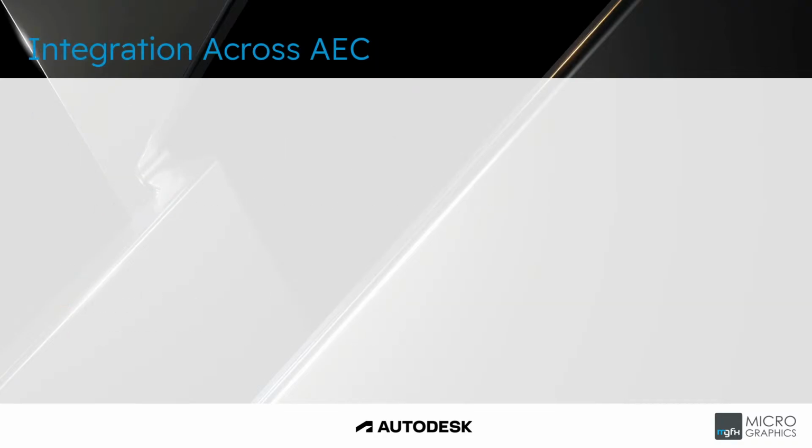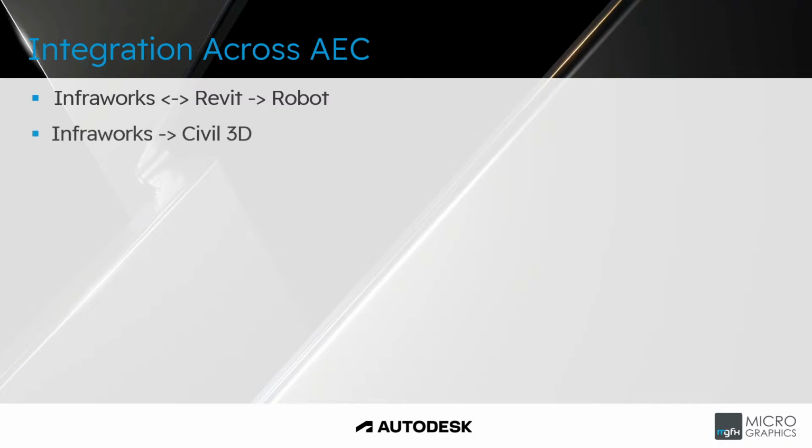Okay, and with our last section, we'll just look at a brief overview of the integration across the AEC collection. So InfoWorks is bi-directional: you can take an InfoWorks model to Revit, and you can take a Revit model into InfoWorks, and then from Revit you can go to Robot. Of course, if you have that terrain within Revit, it will be utterly useless within Robot, and it will most likely be excluded from the transfer. So just something to keep in mind there.